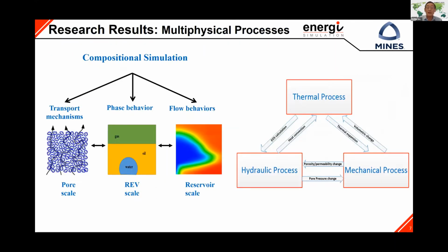Physically, we have thermal, multiphase compositional transport and geomechanics fully coupled. The observation is done at the small pore scale. The formulation we use for fluid transport is at the REV concept scale. The application for field studies is at the reservoir scale.